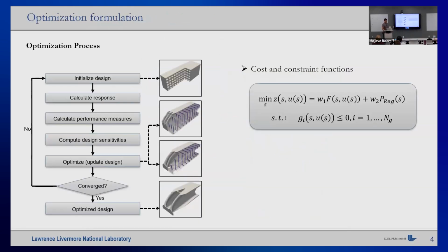Now, what is topology optimization? I just want to lay out the workflow one more time. We heard about this earlier, and I will point out later on where MFEM and all the results fit in. So normally we have this initial design. It's a design field. It can be a density-based field, the way these Airbus people did it, but it could be something else like a level set field. And this field could be defined through some primitives, which are defined through a few parameters, or it could be discretized over the domain. It is a field which defines the geometry.